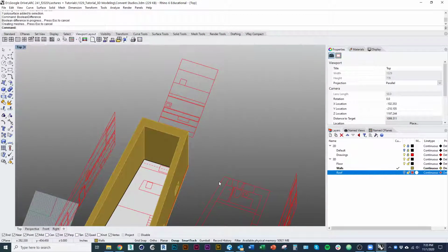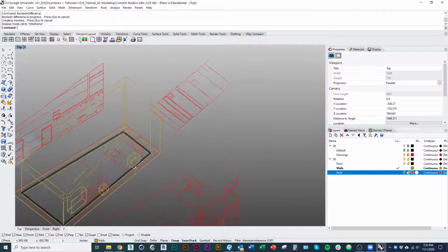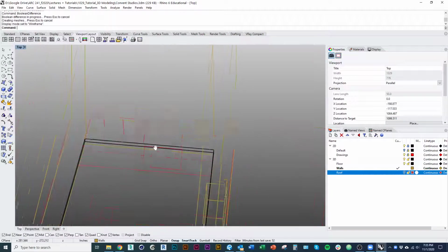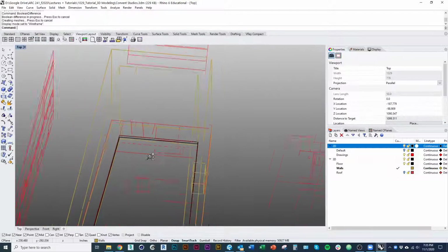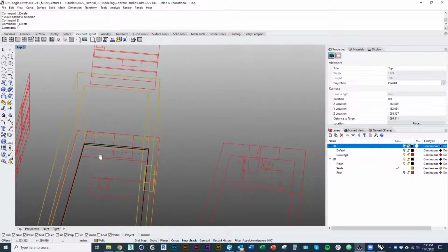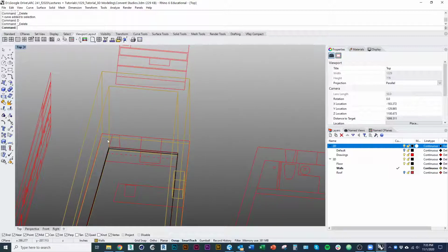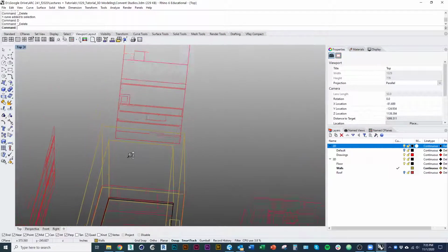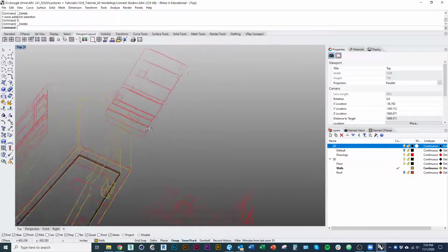One other thing I want to show you, because this starts to get a little bit tricky, I'm going to go into a wireframe for a second. Let's say we have a cutout in our wall that isn't just a straight extrusion. And that exact thing happens in this project. Look at this. There's, one second. Okay, so we had a line we didn't need there. We can see right here that this cutout, this little window opening in our wall, is not a straight extrusion. It's like a tapered volume, and we can see on our interior elevations where that goes.